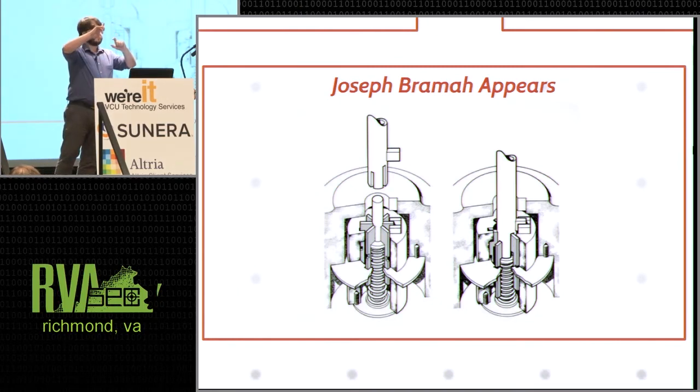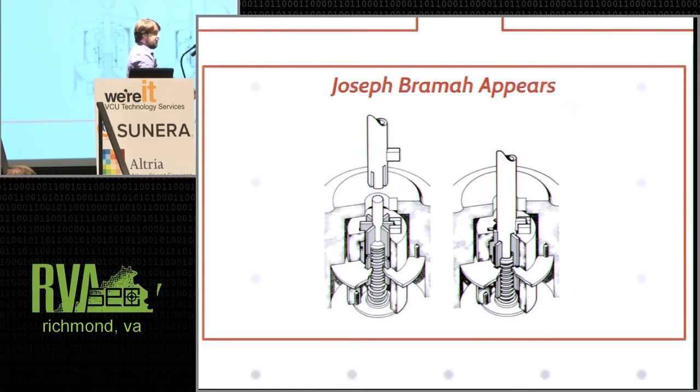The length of the slot corresponds directly to the length of the sliders, which you see at all even depths on the left, and then with the key inserted, all of the sliders will be depressed different amounts by the key. There's a gate in the sliders that correspond to the depth that the key is going to push them to, and then that metal ring in the middle allows them all to spin through.